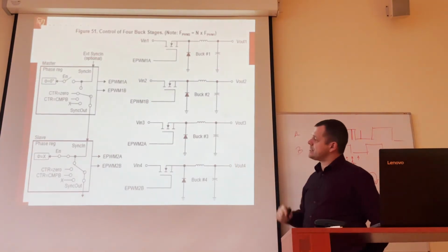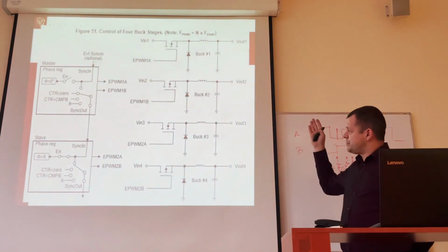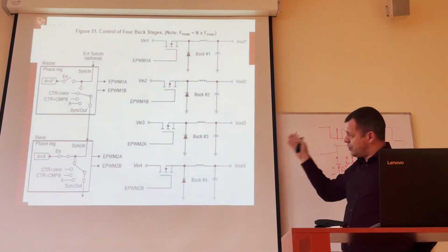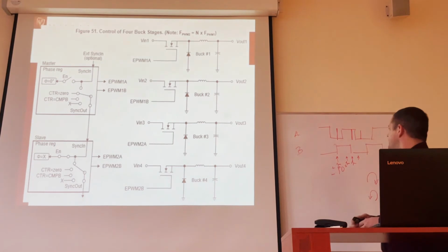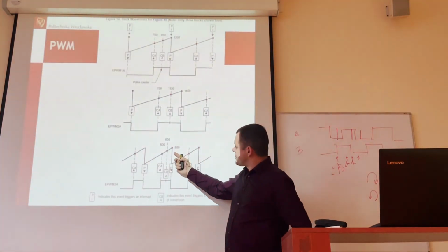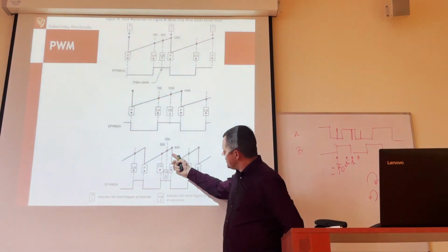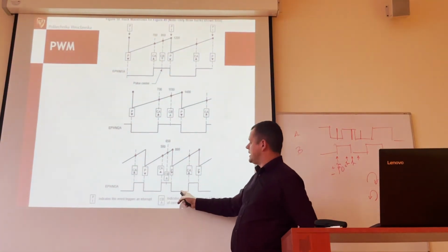That's why we synchronize the timers, to know exactly when the switching will occur. Then we can, for example, make a precise ADC conversion, not here, but exactly, if we know that the switching will be here, then we can do it earlier or later.